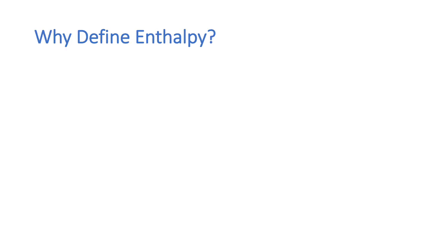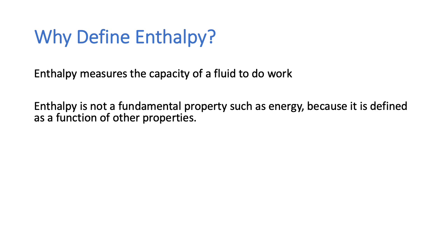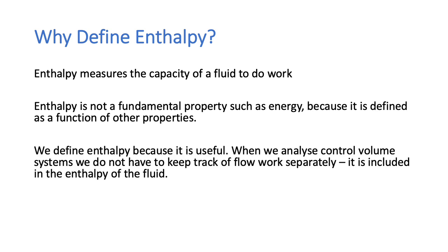So why have we defined enthalpy? Enthalpy measures the capacity of a fluid to do work. Now, enthalpy is not a fundamental property in the same way that energy was, because it is defined as a function of other properties. So we define enthalpy because it is useful. And we will see this, especially when we get into the analysis of controlled volumes, that it becomes very useful to use the enthalpy because we don't have to keep track of the flow work separately. It is included in the enthalpy.